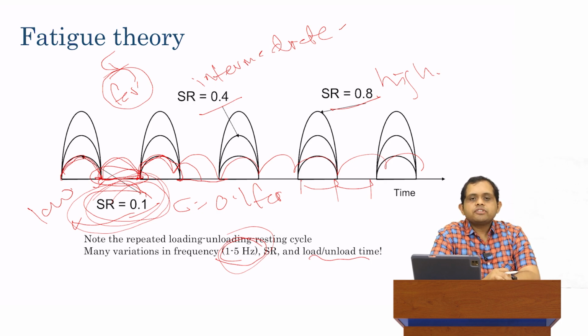So unlike a simple static flexural strength test, which is a relatively easy test to conduct, very well standardized, and we know exactly what number we'll get, the cyclical version is more complicated because we have more choice of parameters. While there are some standard choices in terms of what parameters to choose, they are generally not a single value. There's a decent spread of values we can choose from. So it's a somewhat more complicated test.